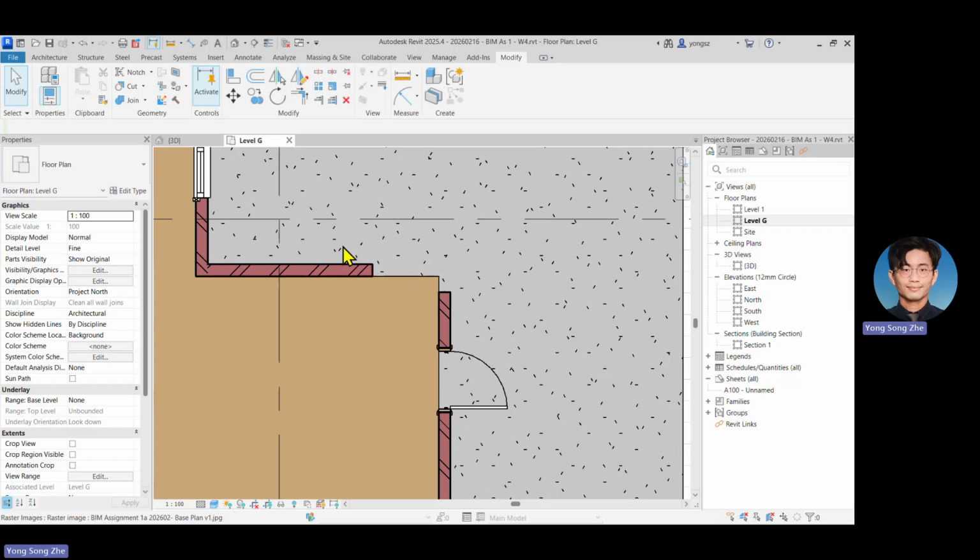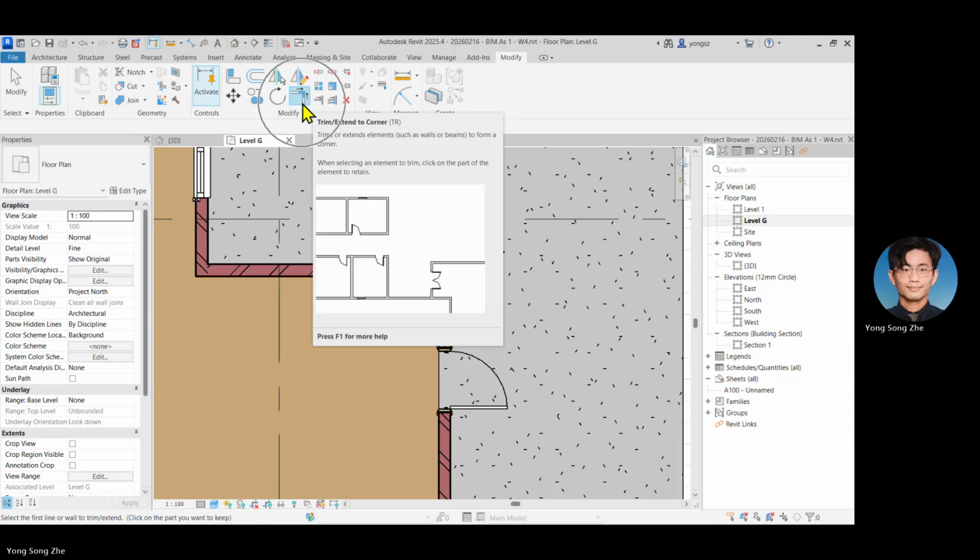TR: T for Thailand, R for Russia. We can memorize it as T-Rex. Then you click the things you want to join. Click this, and I click this. Here you go, joined. This one we call Trim/Extend, and it is here under the Modify tab also.